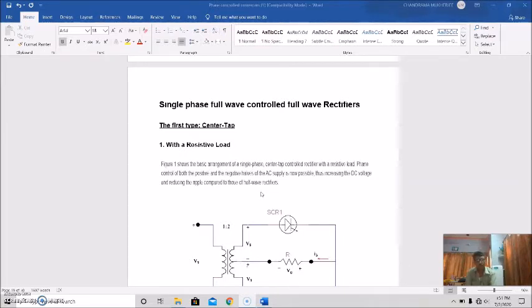We discussed the nature of the waveforms of the output voltage and output current, and how these waveforms change with the variation of the load from resistive to resistive inductive, and how the stored energy in the inductive load is dissipated or circulated using a freewheeling diode, blocking the inductive load from getting back to the source, so that it flows through the load itself.